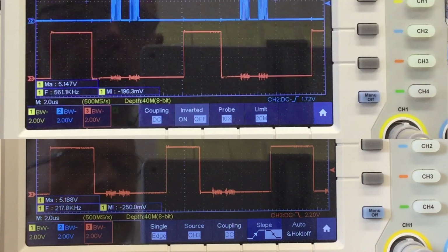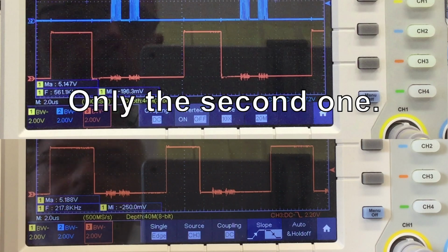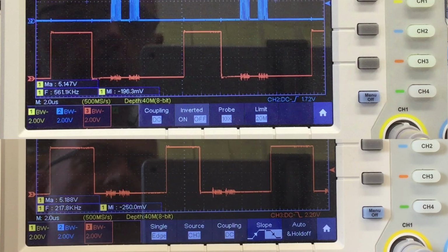Comparing that to the library, you see right away that the chip select highs are longer. The chip select lows are also longer, but the chip select high is where basically nothing happens on the SPI bus. And these longer delays are simply caused by the overhead of calling a method of an object.